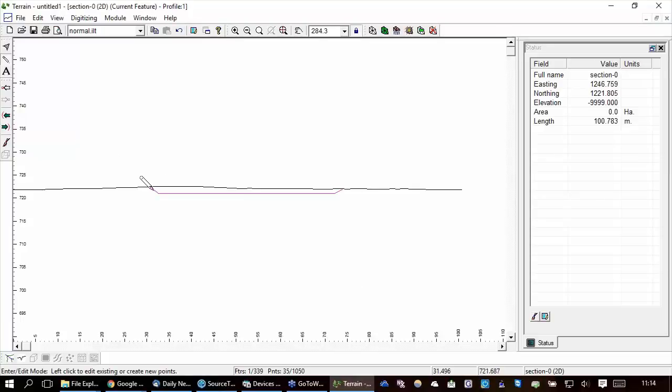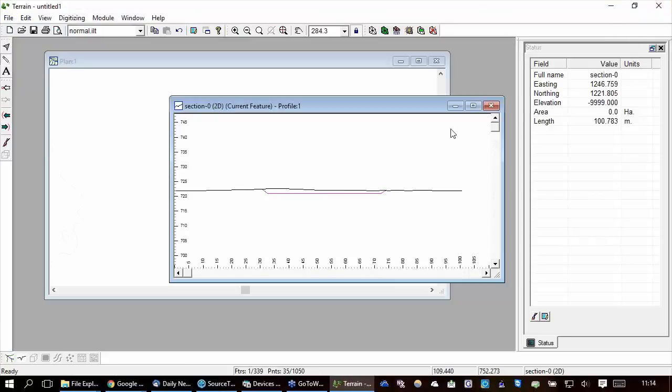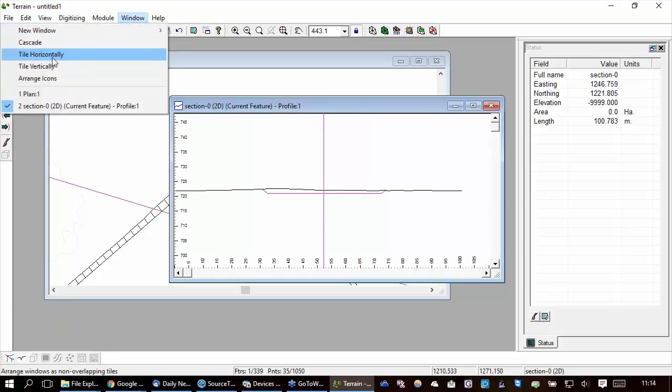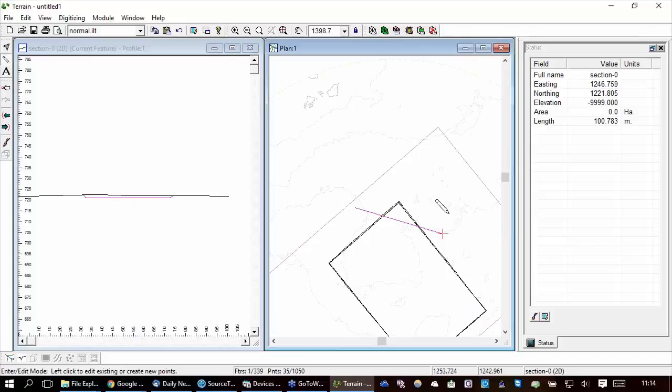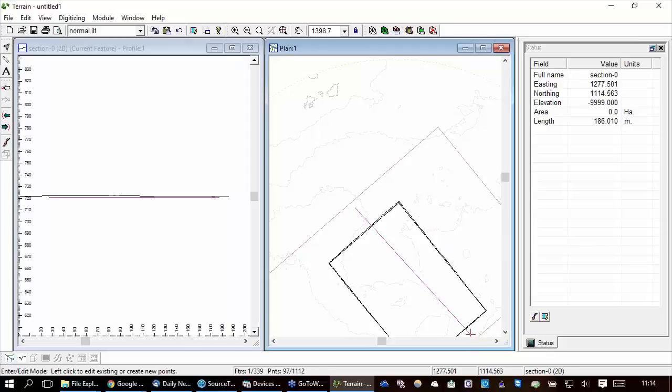Great. And of course, these angles are not the same in this cross-section view because, how should we do this? How about we orient these like so? Because I'm cutting across them at different angles. So if you haven't seen the way draped features work, they're nice in that you can move them around in the plan window and they instantly update in the profile window.